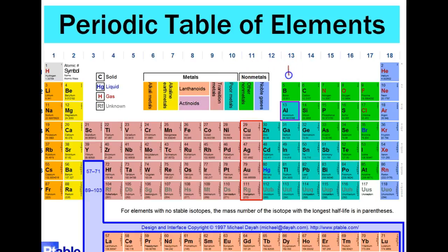Yeah, so electrical power is equal to voltage times current. If we rearrange the formula for I, I is equal to P over V. So what we're trying to transmit is power, right? You understand? So the higher we make the voltage that we transmit it at, what happens to current? Yeah, it goes down.